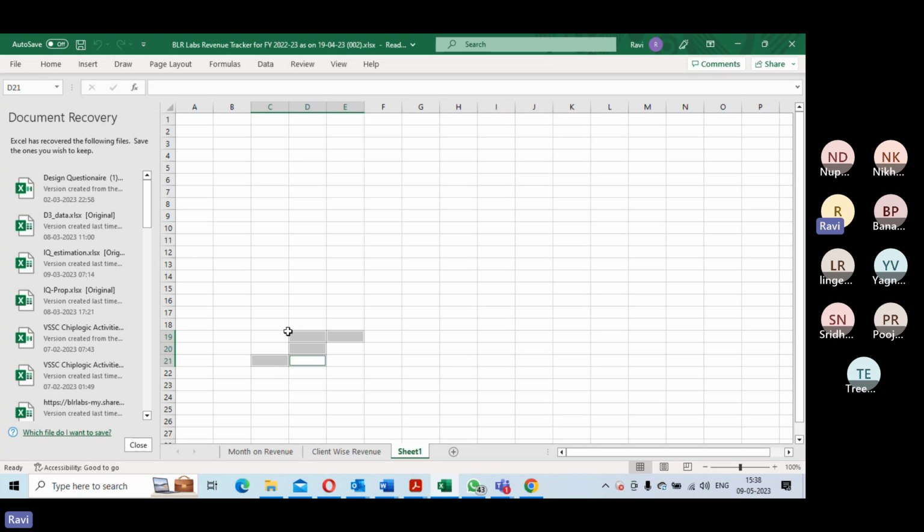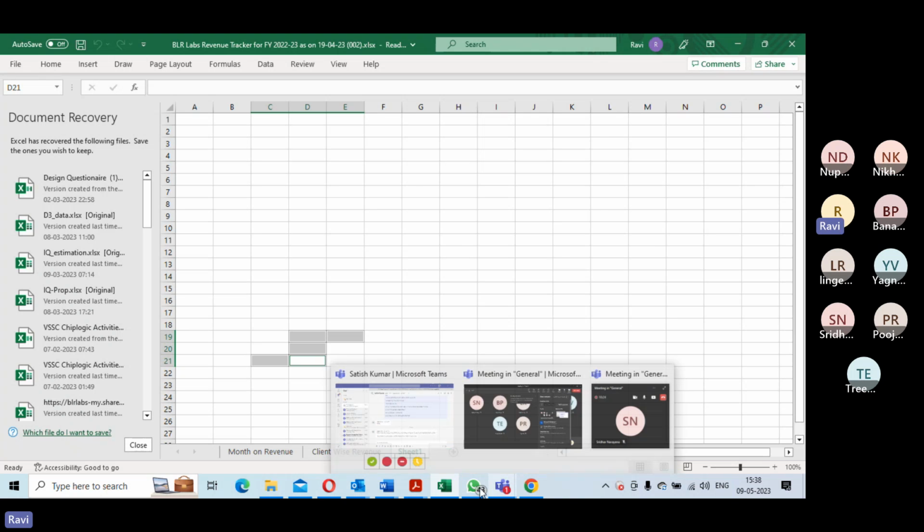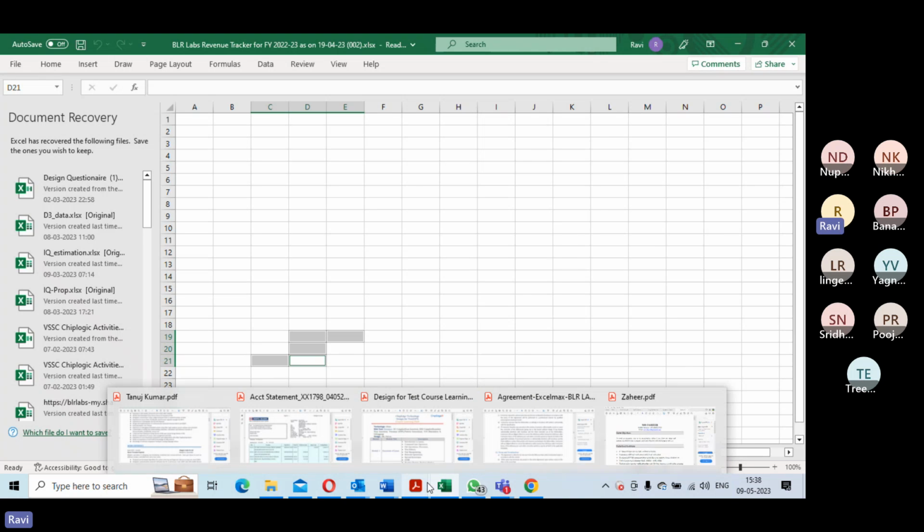Again, you'll come back to 50, 40, and then come back over here. It is 50, 20, and over here 0, 20, and then 0, 0. Like this, you will go and come back to your starting coordinate. That's how you specify the coordinates for a rectilinear block.